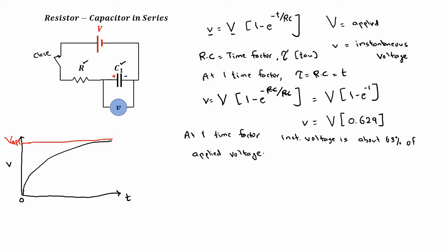Then we're going to repeat the same thing for capacitor 2, and then using the time value and the resistance of the resistor, we should be able to calculate the capacitance of capacitor 1 and capacitor 2. Once we get those values, we're going to create circuits that look like R and then capacitor 1, capacitor 2, a series combination of that, and measure the instantaneous voltage, the lowercase v.